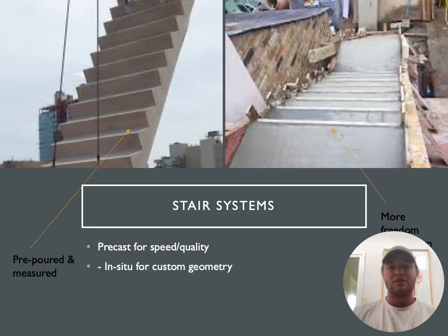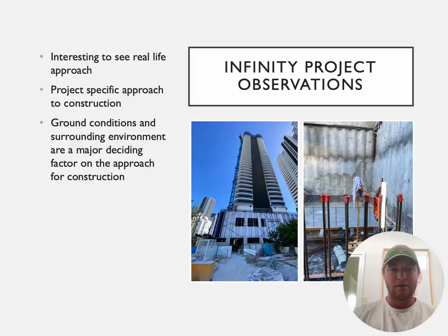High-rise buildings typically use either precast or in-situ concrete stairs. Precast stairs offer speed and quality control, especially in repetitive layouts. In-situ stairs are more suited for unique geometries. Both systems must comply with slip resistance, fire safety, and accessibility codes.